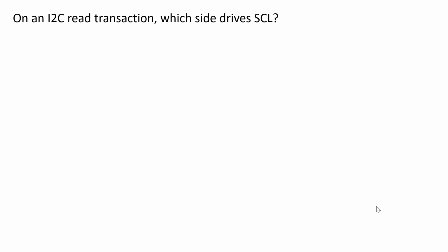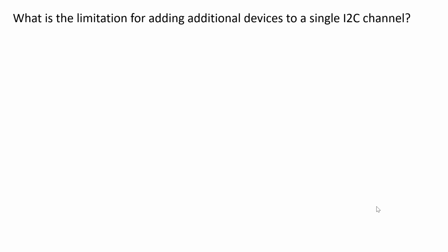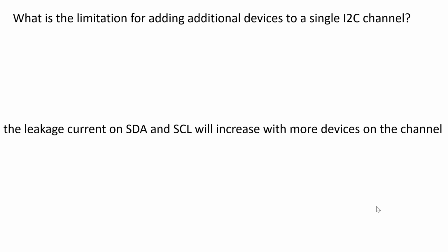On an I²C read, what side drives SCL? That would be the master. What is the limitation for adding additional devices to a single channel? Leakage current.